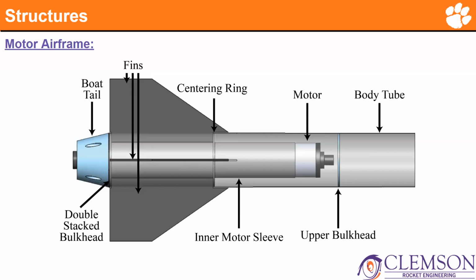So there's a fillet on the forward centering ring, and other than that, it's just the fin fillets. But there's epoxy all around the inner tube to the fins, the centering ring to the fins, and the centering ring to the inner tubes. Okay. So the bulkhead just in front of the motor, how is that one attached? That is also filleted in on the forward side. And the same thing, 5mm carbon fiber? Yes. All right, that should be sufficient.